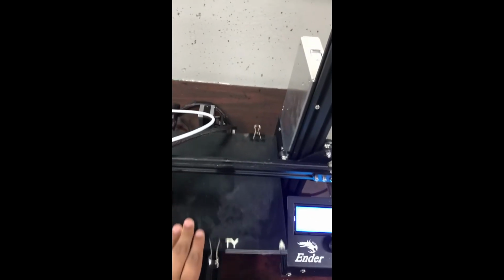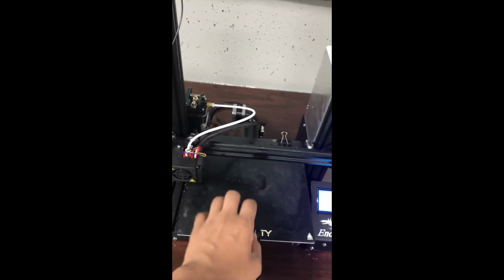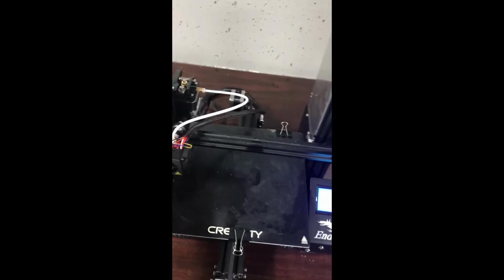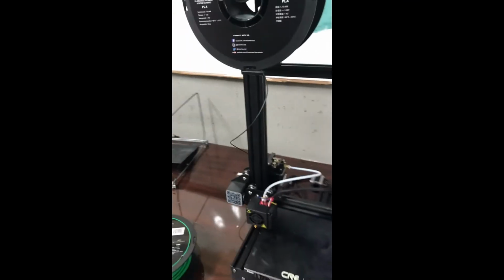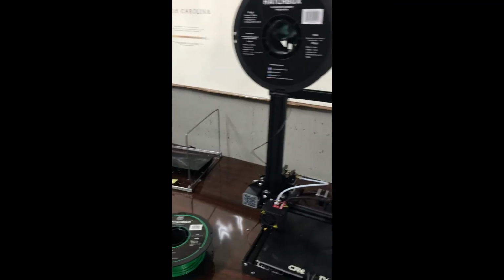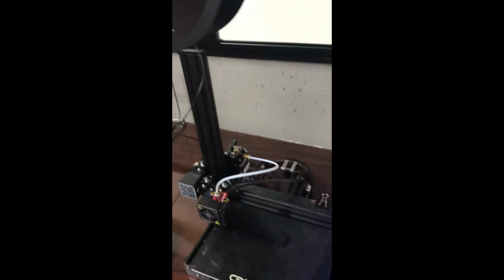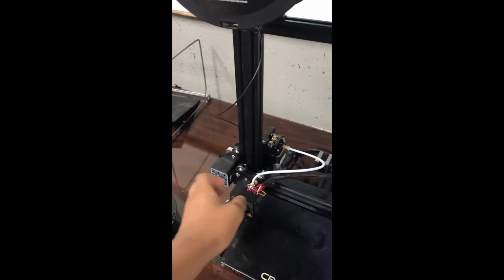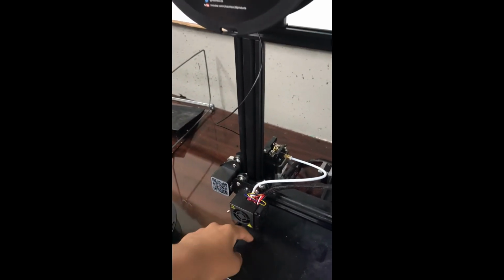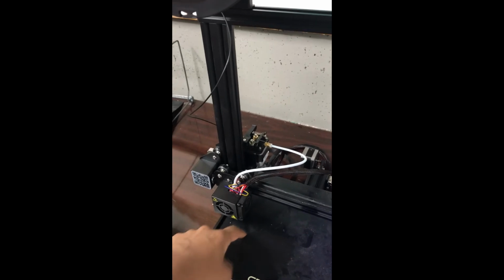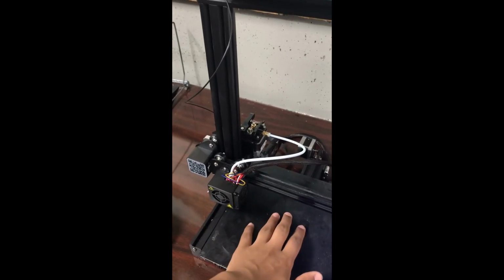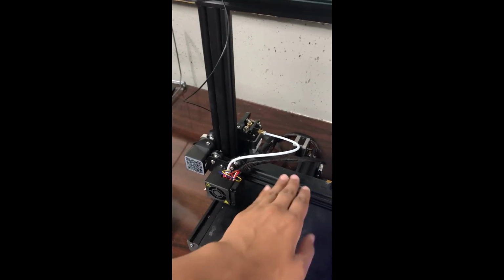So right now the bed is heating up. The bed will heat up to around 60 degrees Celsius, the nozzle 200 degrees Celsius, so it's twice the boiling point of water. And what this 3D printer and most FDM 3D printers do is they take filament and deposit the filament onto a print bed. So it runs it through towards the nozzle, which is heated. As the filament melts, it will be pushed through the nozzle, and then it will be laid down onto the bed, and then every layer below it.